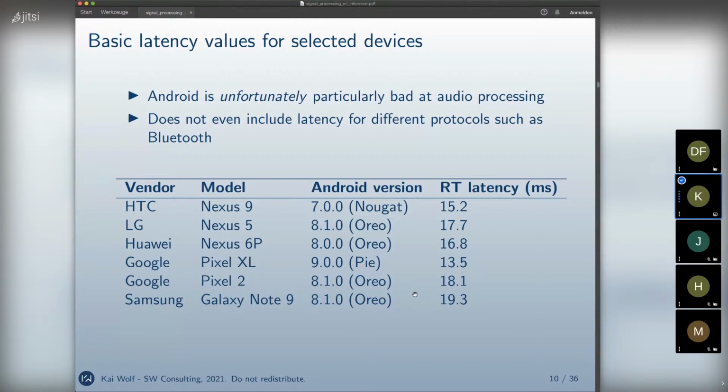For playback music, so I'm watching a YouTube video on my Android phone or listening to music, the latency is usually just fine because there's no real interaction. But if we would talk through the same phone, for instance, and we both would feed our voice into the microphone, then it would be like this latency here. So again, for the Pixel XL, this certain number of milliseconds is fine if we're not doing much more work which adds to the latency. So in this case, say we have like 6.5 milliseconds before it's noticeable.